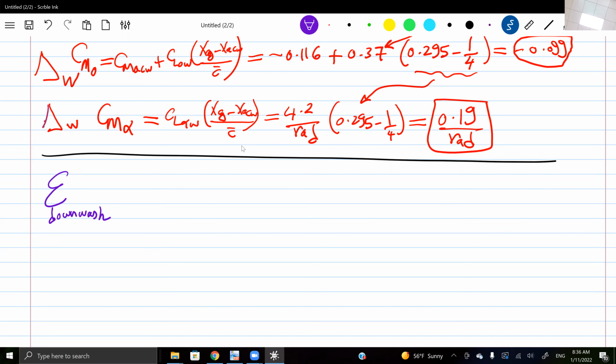Well, it's because of the tip vortices on the wing. So this is why the lifting line theory gives this as a function of the wing lift characteristics. So it's 2CL wing over pi aspect ratio of the wing, even though this is at the tail. So the downwash at the tail is just related to the lift on the wing and the wing characteristics.